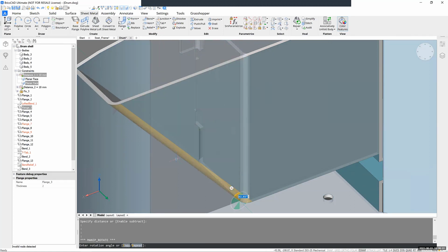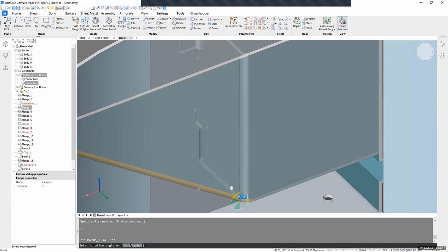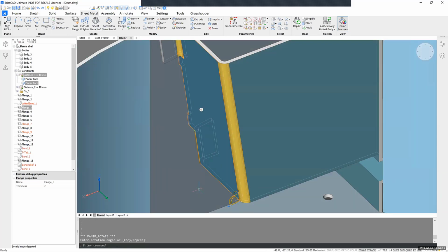Then I select this one that goes in parallel with these flange. And then if I wait a bit, yeah, my preview comes along, and I don't want it to be this exaggerated. I just want 8 degrees. And I can press tab to already see a preview, whether I like it or not. And I press enter to accept the 8.